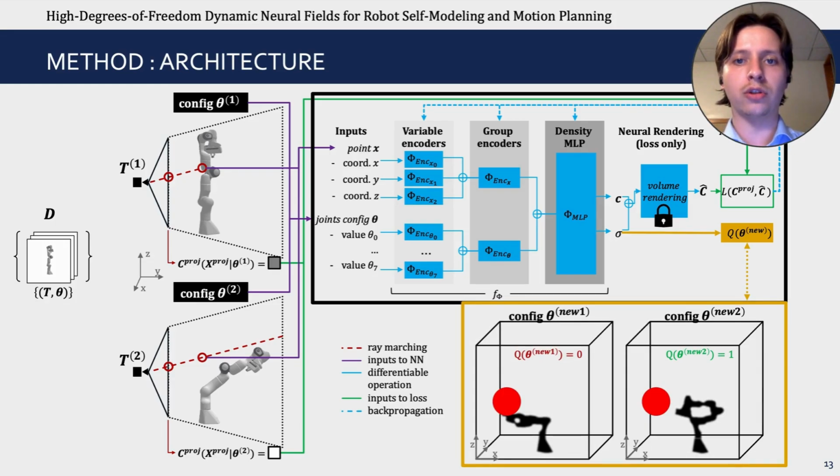To achieve articulated control, we condition the map on all degrees of freedom that inform the observed changes in the scene. For a robot, these are the joint angles. However, learning a 3 plus k dimensional field is challenging, so we introduce two techniques to help the learning process. First, we avoid the forgetting of well-learned value to shape relationships of individual degrees of freedom by incentivizing them to be learned independently via degree of freedom individual MLP encoders. These can retain information about the degrees of freedom's influence when other degrees of freedom are learned because gradients flowing back to them will be zero.